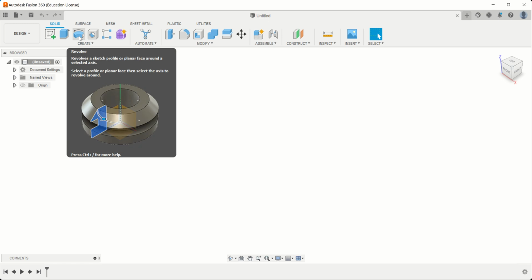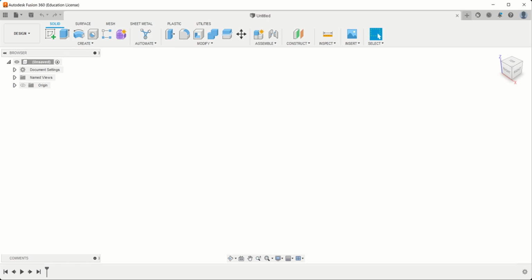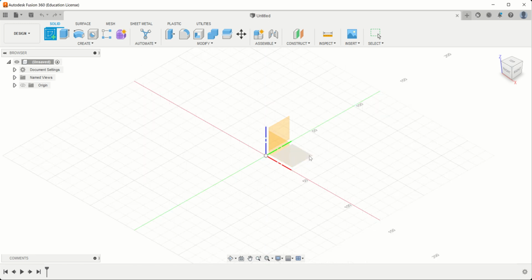And we just have to draw this slightly differently. So if you look on the drawing, you'll see that there's a section line that runs through the middle of the part on the left hand side, and you've got that view AA shown on the right hand side. What we're going to draw is the top bit of the section, the bit with the 45-degree lines on it. We're just going to draw that shape. And this time it is going to be a little bit more complex because we're creating a slightly more complex shape, but we're not going to do all the chamfers first. So let's get going. So once again, create a sketch, XY plane.